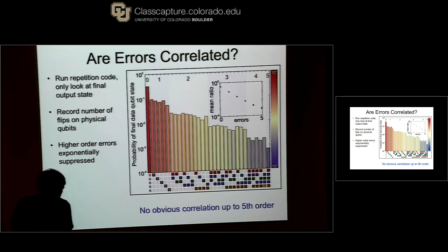So as you can see from the 1D structure, you bring in the wires just from the side. When you build a 2D structure, you have to bring the wires in from a 3rd dimension and build a chip to do that. And also to get all the qubits to tile together well, you have to compactify the resonator readout near the qubit so that you can tile the resonators as well with the qubits. And then you have to wire that up and then build structures so that you don't get a lot of crosstalk from all of that. So there's a lot of chip design and engineering going into doing all that. And it's taken us 4 years to figure out how to do that.